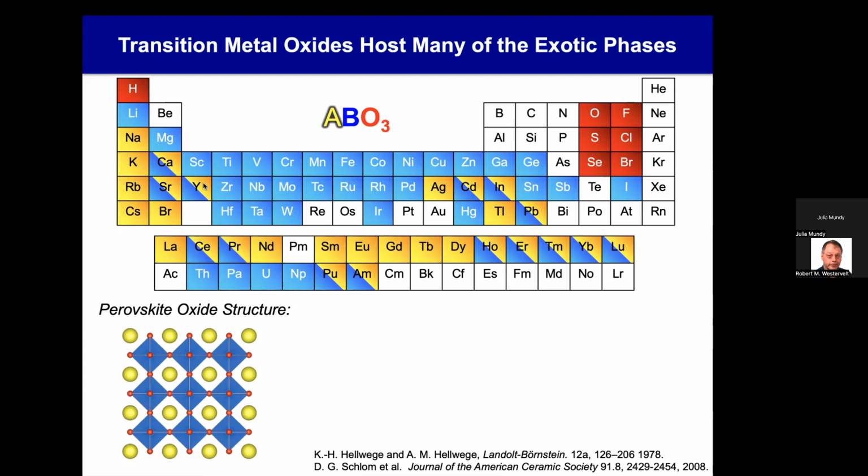So we think of these ABO3 structures, perovskite, where this is an A site cation that's sitting here. These are mostly ionic materials. There's a B atom in the center, and then it's being surrounded by a cage of 6 oxygen atoms. The name perovskite actually comes from calcium titanate. You can go check it out in the Museum of Natural History across the street. There's perovskite, it's calcium titanate. You can dig it out of the ground. It's one of the most common of these materials.